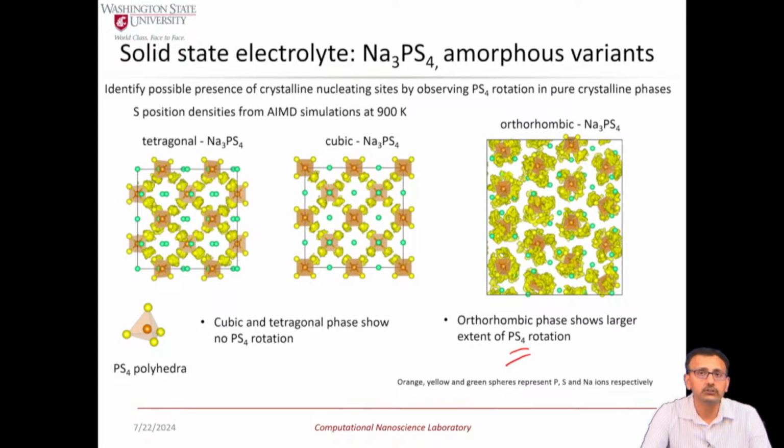Ions. Yeah, sure. We look at those defect effects. In fact, one of the reasons amorphous structures have a higher ionic conductivity than the crystalline counterparts is because of the free volume for ion hopping that it opens up in these amorphous structures, because of less short range and medium range order, which opens up new ion hop pathways.